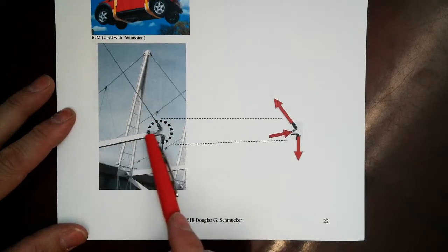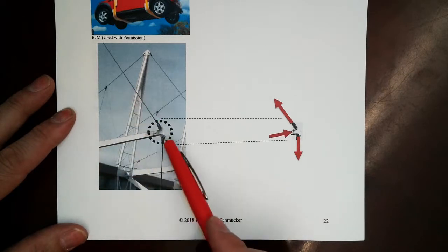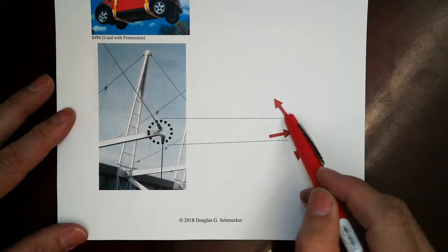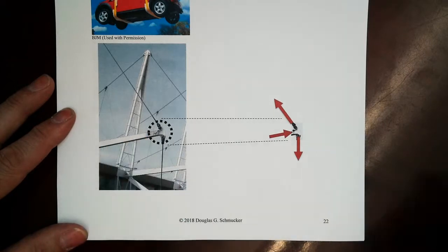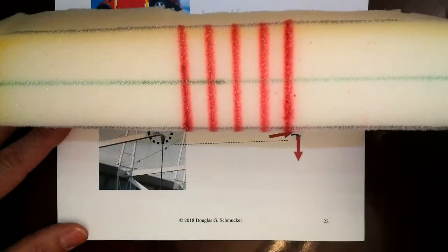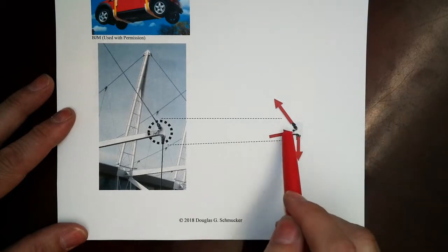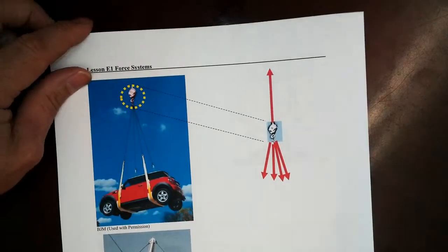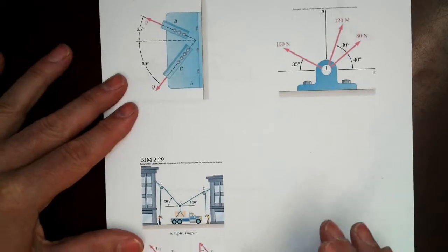You've got this little post coming out here, really another spar. You've got a cable that way, and when we cut that free body diagram, remember, cables are in tension, going away from the body. This big thick thing can take compression, just like this little beam could before. That can push on the joint, so it's going towards the free body.